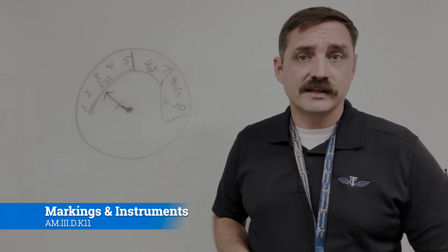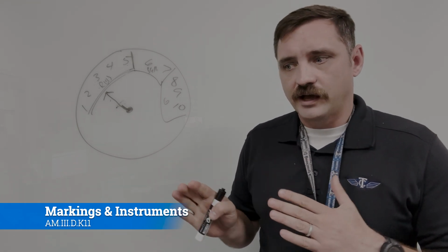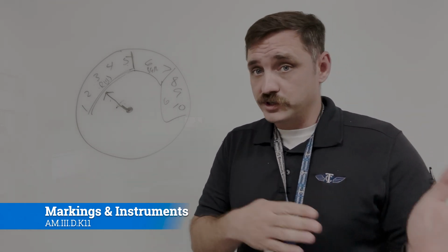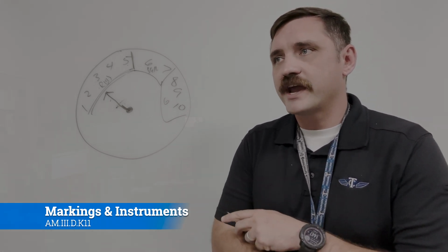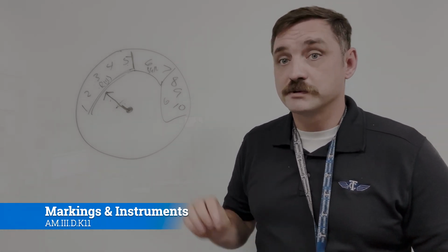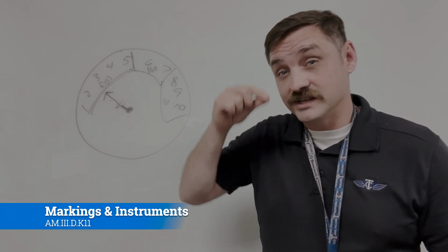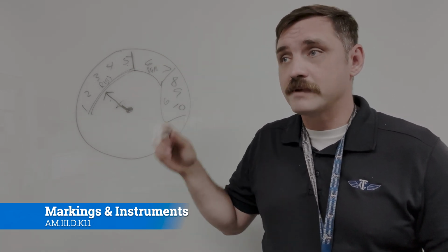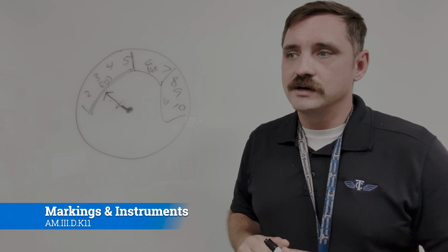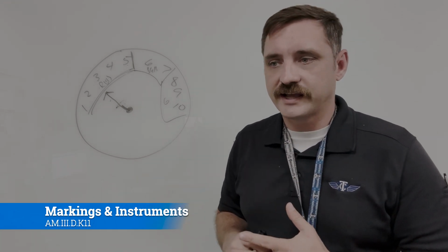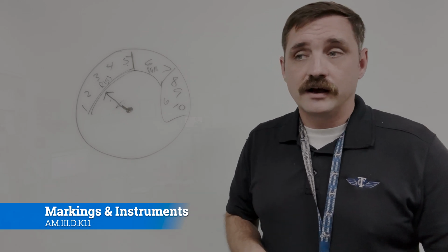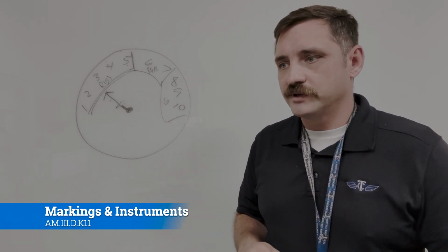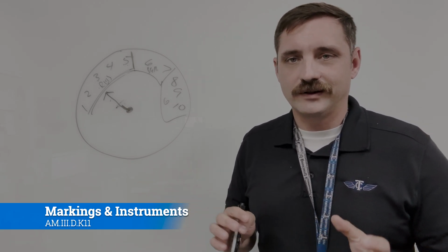And this could happen with any number of gauges that are out there. The troubleshooting steps are always going to be about the same. There's other ways that you can check for gauges, and a lot of times, especially in the heavy commercial world, you'll have access to the CMM. It's the component maintenance manual, and that will allow you to access another set of procedures where it'll say, hey look, we expect this thing is wrong. Let's try it.